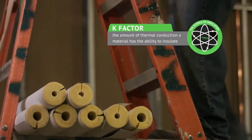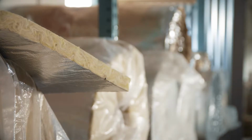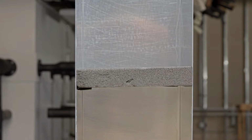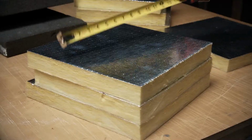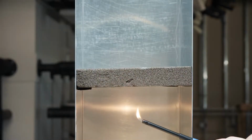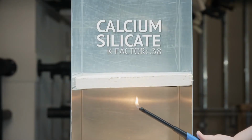K factor is the amount of thermal conduction a material has the ability to insulate. The lower the K factor, the better the insulation. In most cases, the insulation materials we work with have a K factor of less than 1. To determine the K factor of materials, the manufacturer would measure the number of BTUs that would pass through a 1-inch thick material that is 1 foot long by 1 foot wide in 1 hour, with the two sides having a differing temperature of 1 degree. An ideal material will have a low K factor. Fiberglass has a K factor of 0.25, whereas calcium silicate material has a K factor of 0.38.